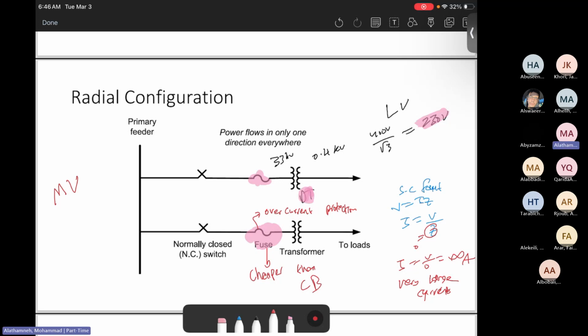All right, now we get it. Since we have a fuse and the fuse will take care of everything, what's the point of this switch? Again, we said the circuit breaker or the fuse will take care of it if there's something wrong. But how about these switches? What's the point of having these switches since the fuse will take care of everything? The main reason is maintenance. Sometimes we need to do some maintenance, but the fuse is not melted. Then you can disconnect the power manually by going there.